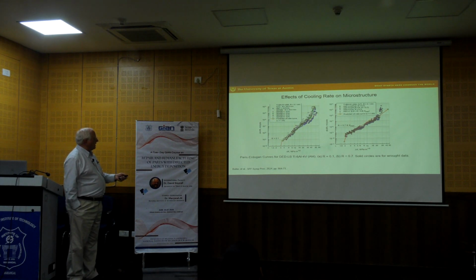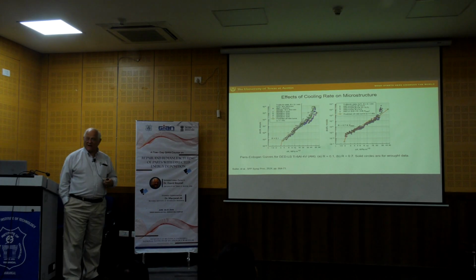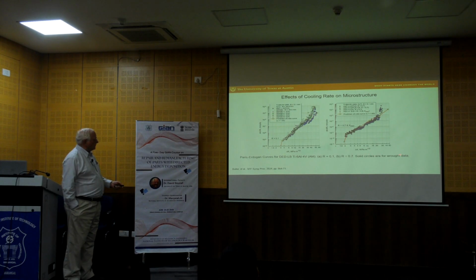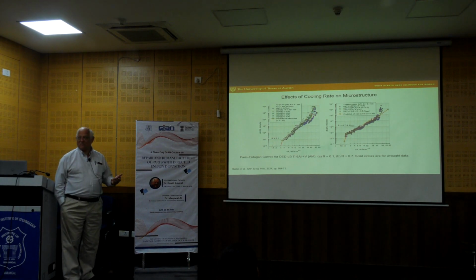And what we see here, if you look carefully, let's just look at 0.1, which is the more aggressive kind of fatigue test. What we see is that these blue circles that lie down here are the conventional, the raw data, right? Everything else is additive manufactured, and so what we see is that really at every point the additive material has a higher Y value than the conventional material.